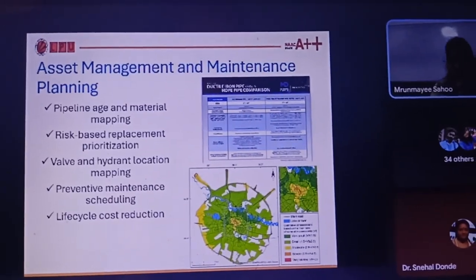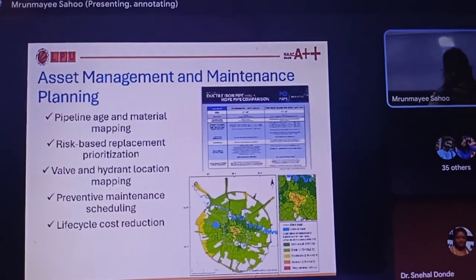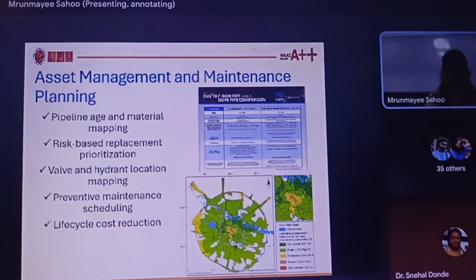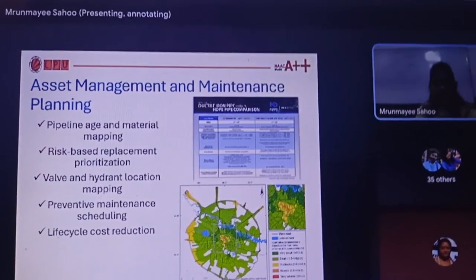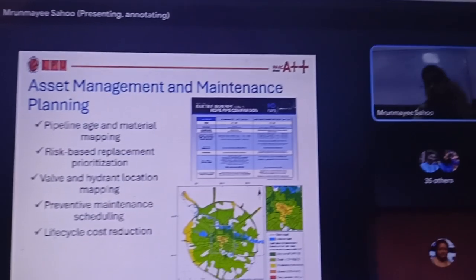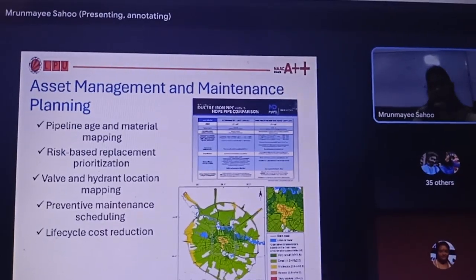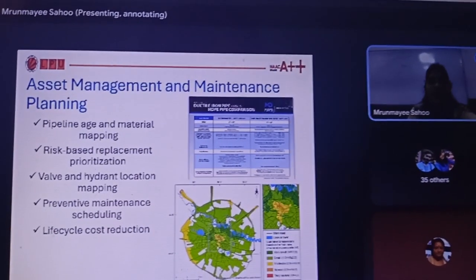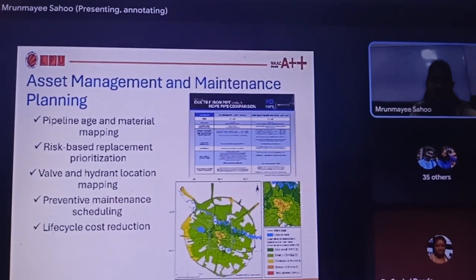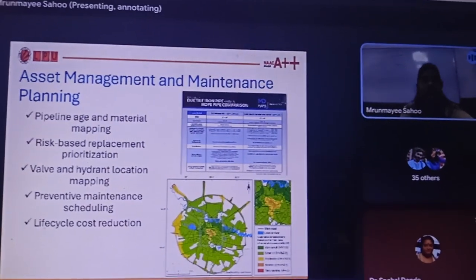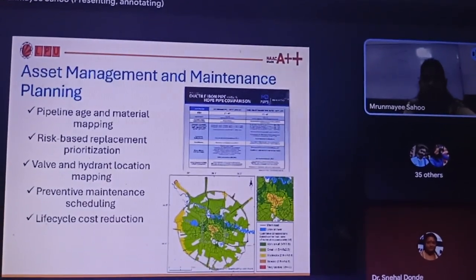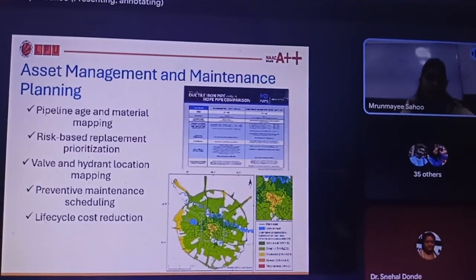If the pressure fluctuation is high, then there will be some kind of non-revenue water, someone is taking the water in an unbilled way, or there is some kind of leakage. So pressure detection is very much required and must be integrated with GIS. So again, how to check it? When we check this, we measure the minimum night flow. We say it is MNF.